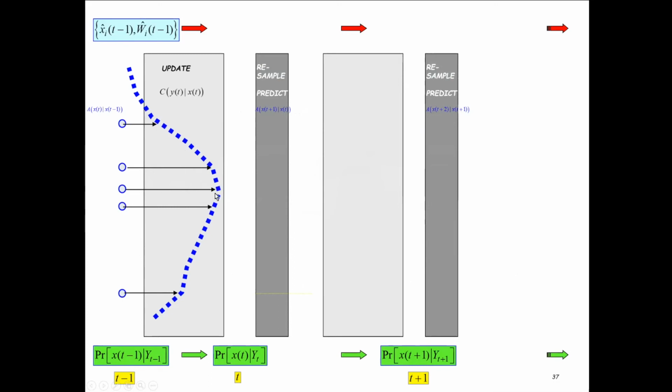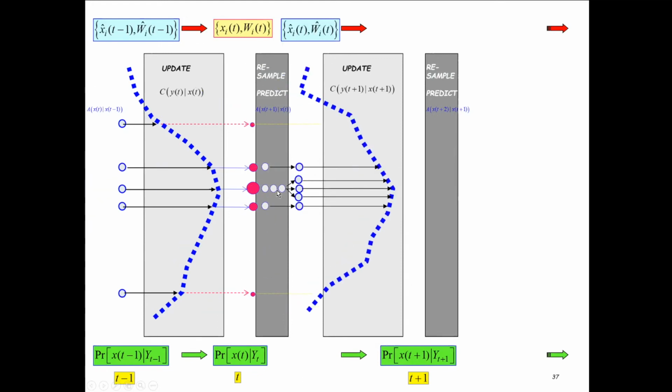So you can see these are the weights, these are the high probabilities, we're just sideways. And so this is the probability. Now, if I go through the update step, well, now I get these large probability weights, and these are the small ones. And now I do the resampling into these numbers of weights to represent each one. Then you can see we've deleted the weak probabilities and we've progressed to the next level.